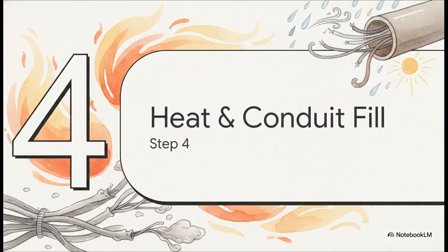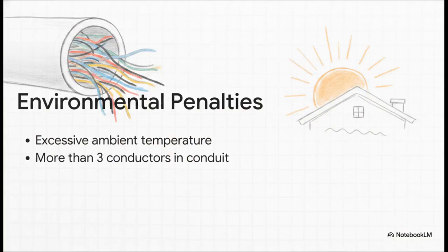Let's move to Section 4 and see how this builds: heat and conduit fill. Because time isn't the only thing testing these wires. Cramming too many wires into a single pipe or running them through a blazing hot attic drastically reduces a wire's ability to dissipate heat.